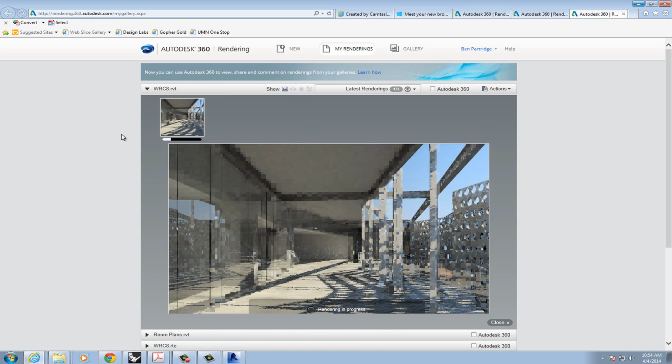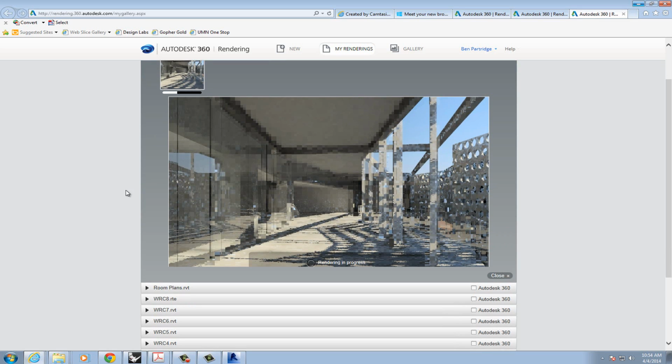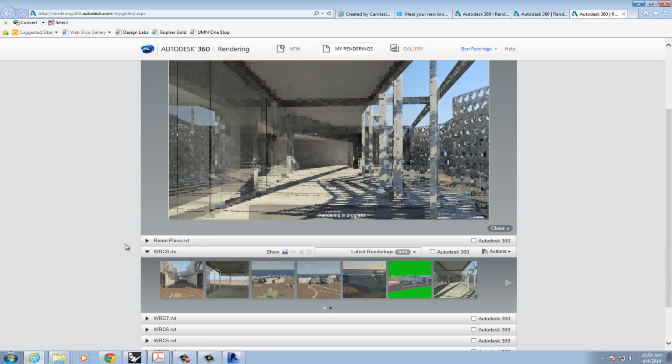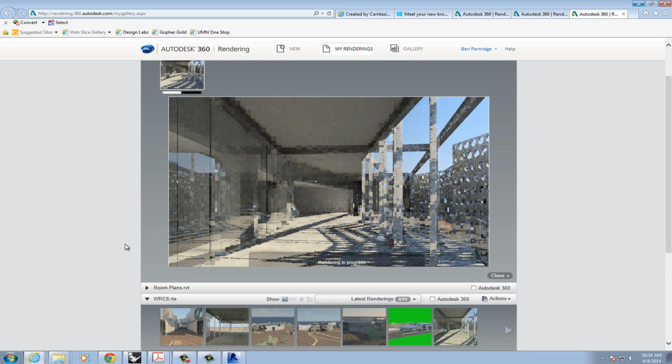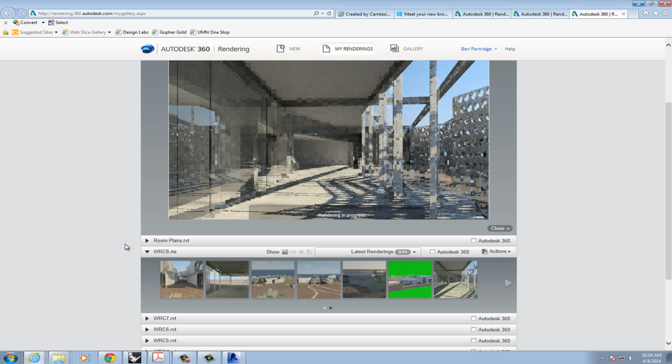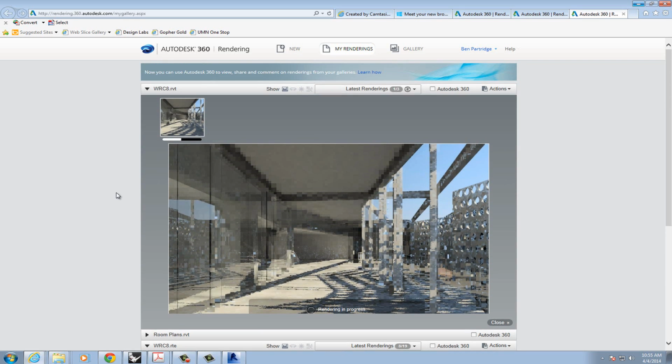So, for example, for a night shot, if that's your question, when rendering in the cloud, if you just leave it on standard, it's always going to put sunlight in. So either you need to change the time of day to nighttime, or you would turn off the sunlight and only render your artificial lights within. But then don't you have to mess with photometrics? Oh, absolutely. You can get really in depth with this depending on what types of lights you're using. IES lights are going to be an exact representation of what that type of light is going to produce, and then you could use that to analyze all of your lighting, whether it's artificial or natural.